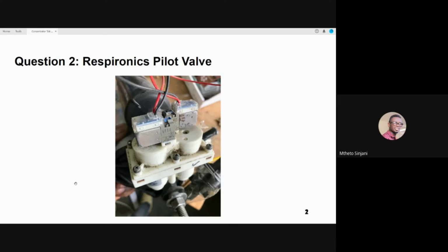After that, you put back the beds in the concentrator, and then you test for leakages using some soapy water while the concentrator is on before you close it. The last thing to check is if the valves are switching. Make sure the compressor is placed correctly and the fan is working perfectly.